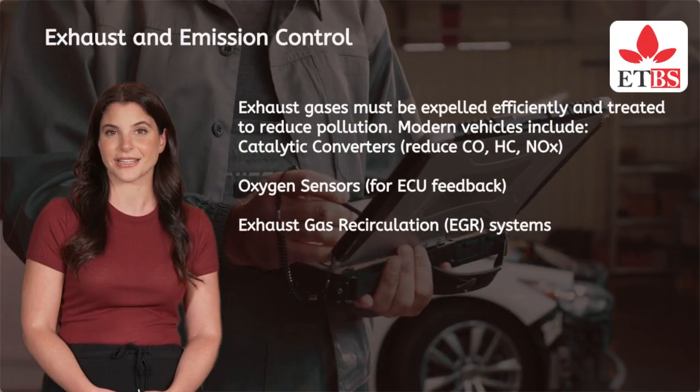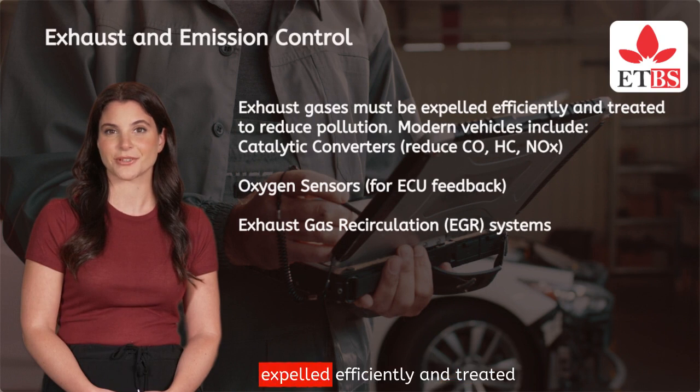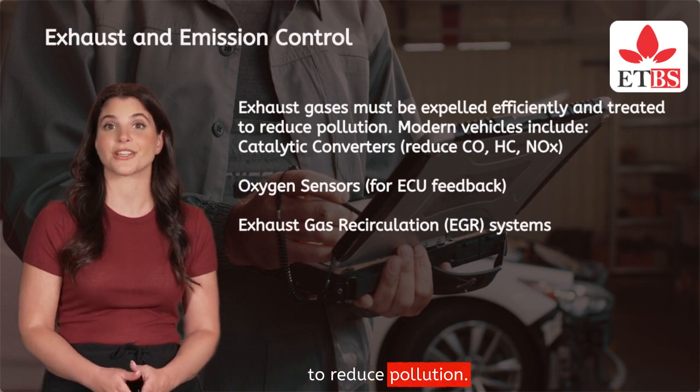5. Ignition systems. Conventional ignition, mechanical distributor systems with breaker points. Electronic ignition, sensors and ECU, engine control unit, controlled, more precise. Diesel ignition, relies on high compression, no spark plugs. 6. Exhaust and emission control. Exhaust gases must be expelled efficiently and treated to reduce pollution.